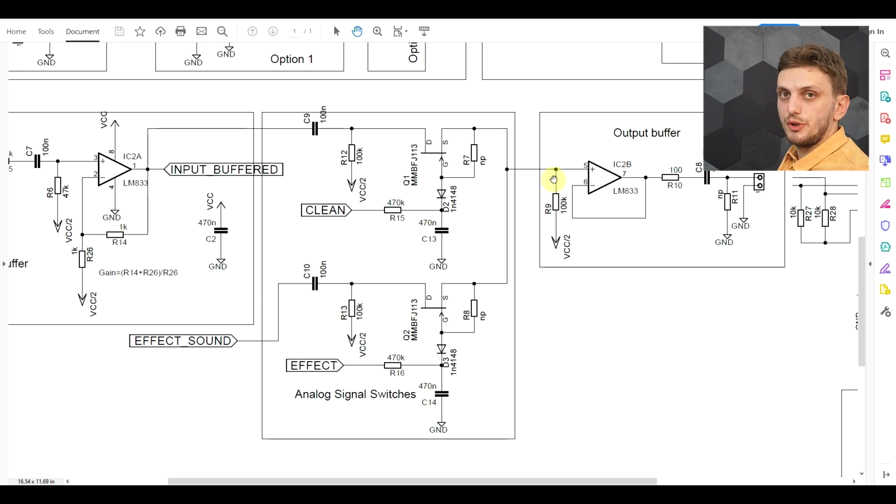Basically, the purpose of these three resistors is to keep the reference voltage potential at these three points around our supply divided by 2. And by decreasing their values, these three potentials are much more stable. So basically, by making these modifications, I went from a very audible popping sound to something that you can barely hear. So the final thing to do is actually insert our effect and see what happens.